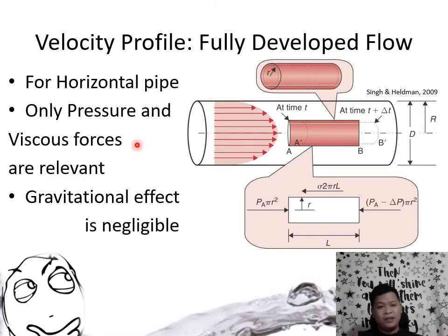Okay. Gravitational effects are negligible because they are much weaker, the downward pulling force. Especially when the flow is horizontal, because the push along the horizontal plus the effect of viscosity is much stronger. That's why it is uniform, because if there were a gravitational effect, it would not be uniform along the middle, it would droop a little, no?